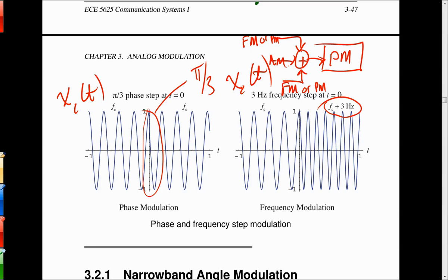So are these two modulation techniques directly related, or are they just two ways to do phase modulation? Could you get one from the other? Yeah. They are two different things in the sense that in phase modulation the message goes straight on through, and in the other it gets integrated first. So don't think of them as just being tracked together in the notes but not directly related. They are directly related through the integral or the derivative, okay, as far as that's concerned.